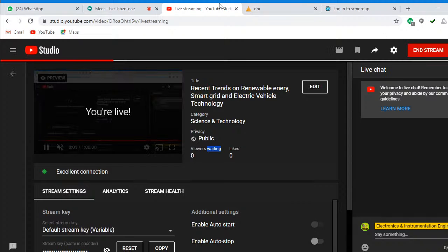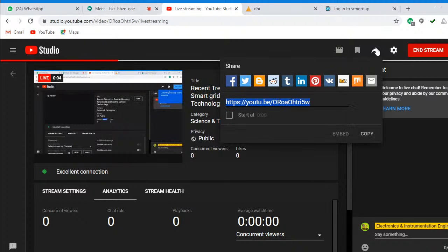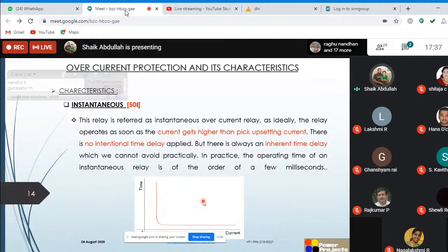Because the sensing device has to sense the fault current, and then there is the relay operating time. Once the relay operates, there are some logical operations, everything is computed in my relay. So once the relay decides, okay, this is a fault, I'm going to trip, it will give the trip command to the breaker. Thereafter, the breaker has to start its operation.